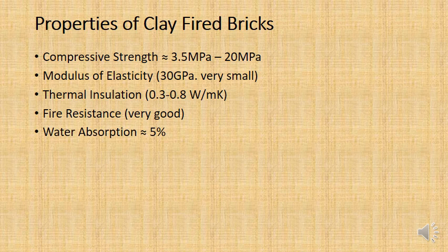It also has a water absorption, so this is basically porosity. This is the absorption capacity of 5%. So this means that if I weigh the clay-fired brick and it weighs, let's say, 100 grams, then I soak it in water for maybe 24 hours, and then I take it out of the water and I let the surface dry off and I weigh it again. It might weigh 105 grams. It's increased in mass by 5%.